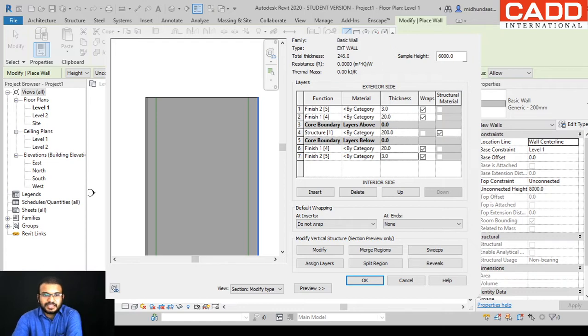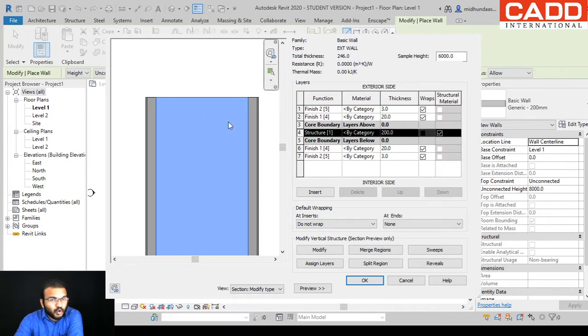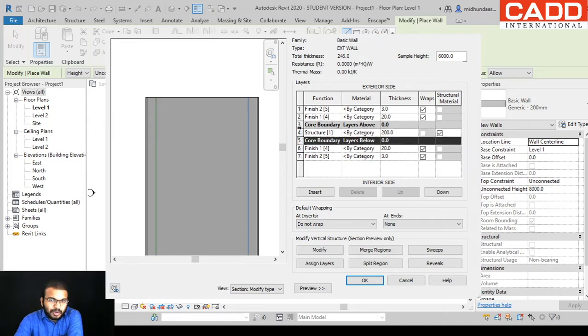So what we did is prepare the wall layers properly with the thickness but not the material. Okay, so what I am going to do now is add a material here. First of all, let us add the center or core component material as brick. Whatever layers are there inside the core boundary, you should give. See, this is the core material.